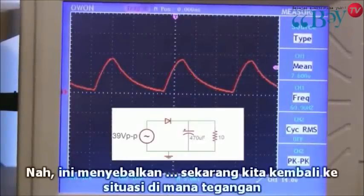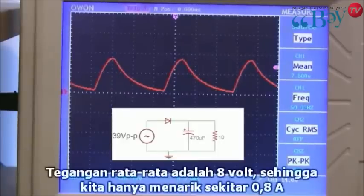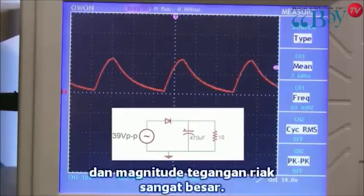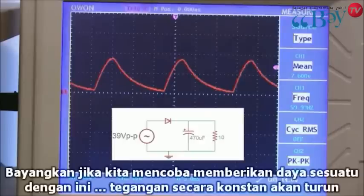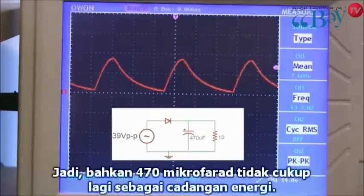Well, that sucks. Now we're back to the situation where the voltage is sagging in every cycle. The average voltage is 8 volts, so we're only drawing about 0.8 amps, and the magnitude of the voltage ripple is just huge. Imagine trying to power something with this. The voltage would constantly drop so low it would never even stay on. So even 470 microfarads is just not cutting it anymore as an energy reservoir.